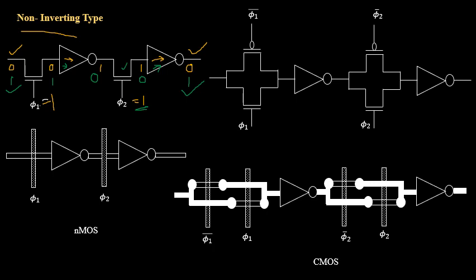operation. Similarly, if I want to check in case of your CMOS design, I will make this equal to logical 1 state. If phi 1 is 1, obviously phi 1 complement is 0. Both the transistors, PMOS and NMOS, are in the on condition. If I apply the input as equal to 0, it will pass through this particular NMOS transistor, so that it will yield me the exact logical 0. 0 is passed through an inverter, which means 1 is the obtained output.